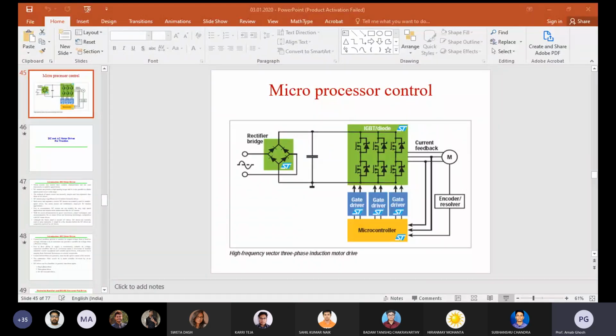If you go through that subject, you can see that we analyze the entire process in different transformation modes, such as the Clarke transformation and the Park transformation. We are transforming the rotating magnetic field to some specific axis. Sometimes we transform it to the stator axis, sometimes to the rotor axis.